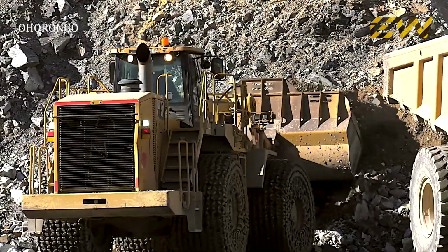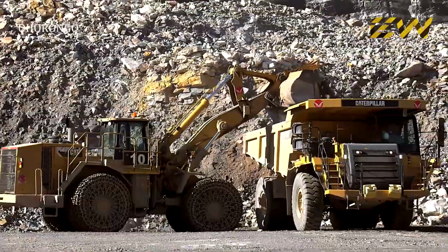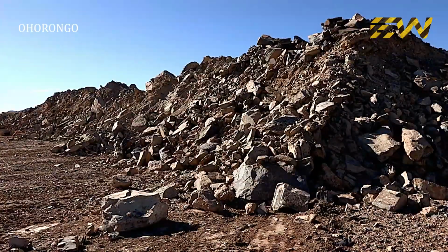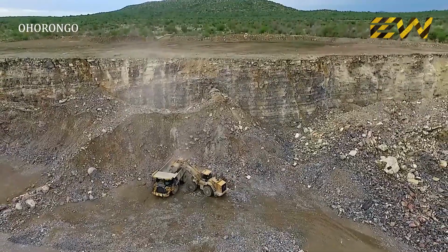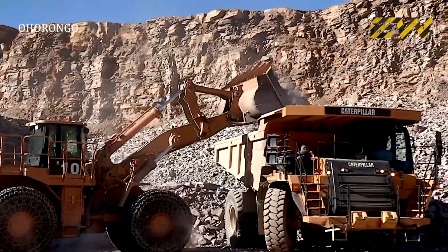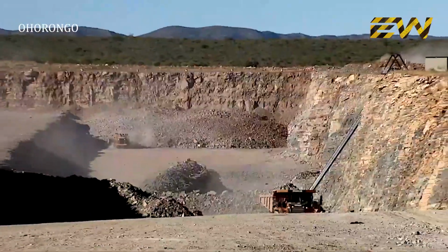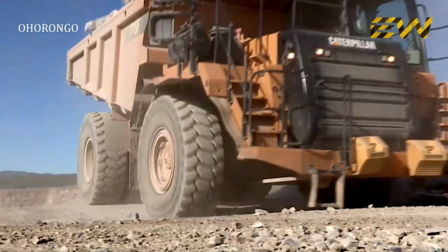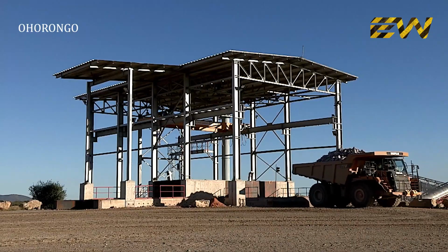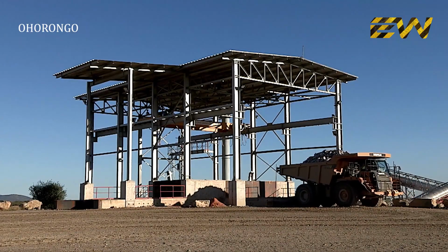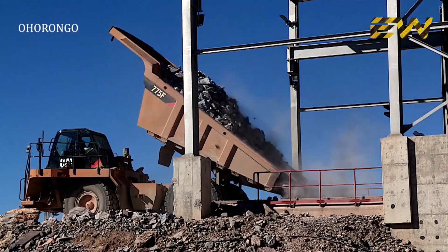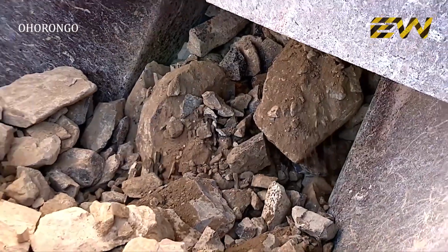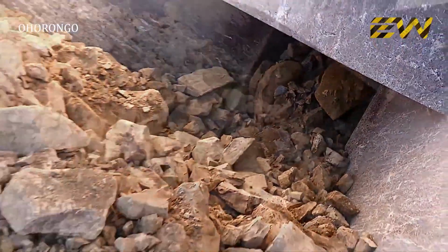Raw materials for the production of cement consist of limestone, shale, and marl, which are available in large quantities in the quarries, and other ingredients such as iron ore and gypsum are obtained from mines. The raw materials are loaded onto haul trucks with a loading capacity of 60 tons each. These raw ingredients are transported in specified ratios to the crusher, where they're ground to the consistency of rough gravel. The crusher can handle 600 tons of raw materials per hour.